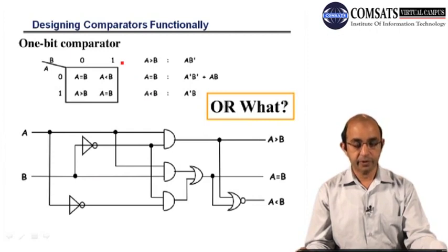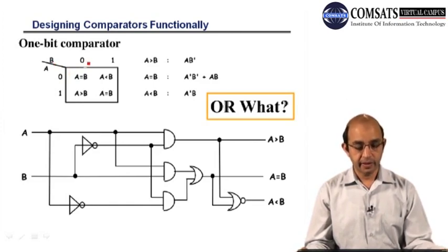Okay, now we have to discuss the comparator. If we have to compare two bits, a and b, let us draw the truth table. We have b in the row direction and a in the column. Here a is equal to b, both are equal. Here we have a 0, b 1, so a is less than b; here a is greater than b; and a is equal to b. So this is the 1-bit comparator, using these simple logic functions AND, OR, NOT.